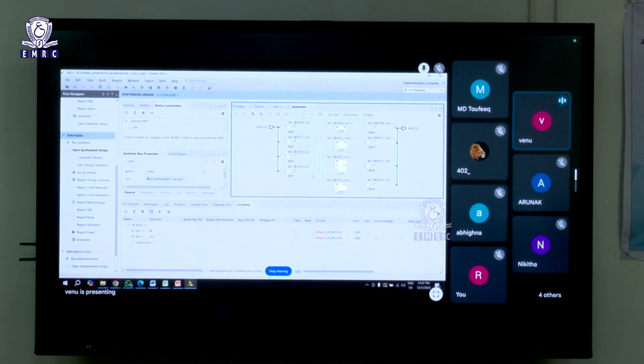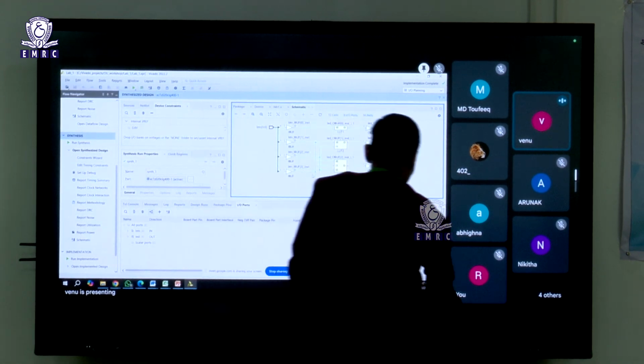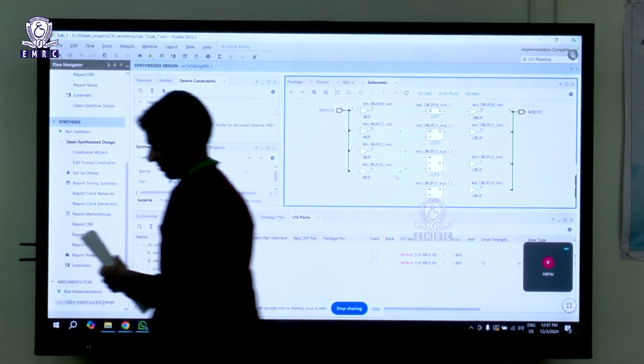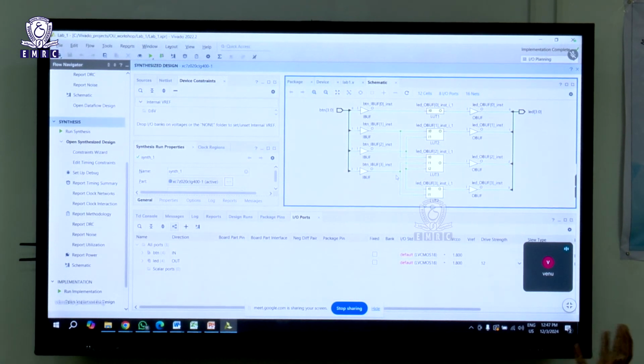Right. So, earlier I have told you that you need to store the gate level data onto the LUTs. You cannot directly implement gates on the FPGA, but rather what we are doing is we are implementing the logic on the FPGA, right. We are saving that logic onto the LUT. So, here we can see that we are using LUTs rather than gates. And to align with how the FPGA works, we also have buffers.